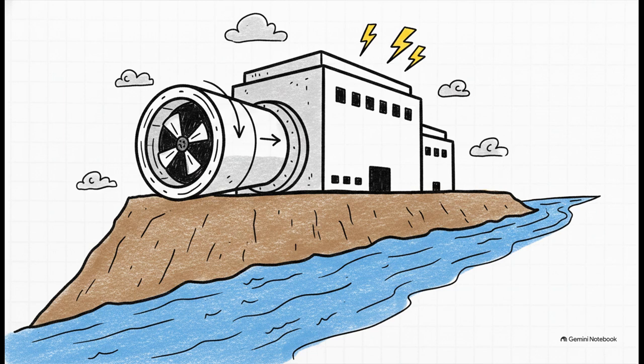The answer? Flood risk heavily outweighs water access. Inundation risk is the absolute deal breaker here. You absolutely must prioritize drainage and elevation above all else. You just do not compromise the safety of a Tier 3 facility just to score some cheap water cooling. Instead, the right move is to build on elevated land and solve the cooling problem using closed-loop systems.